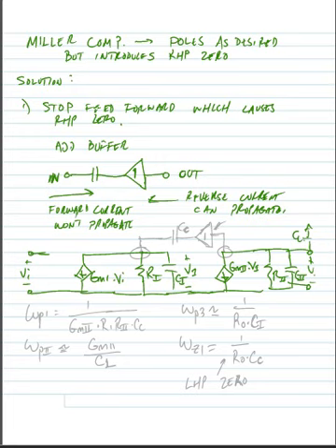So with this buffering compensation, we imagine placing our compensation capacitor with the buffer going from our output back towards our input. Our buffer has a gain of 1 and our compensation capacitor is here. Now if we do KCL at the input and output nodes, we would find a couple of things change.